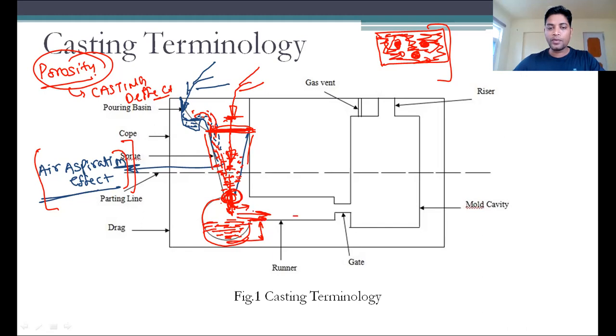then it passes through this runner. This runner is a horizontal passage, okay. And we also use this runner because now the material is moving horizontally. So what will happen in the material, the more dense particles will try to move at this area, a particle which has a very high density will try to settle over the bottom of this runner, and the particles or molecules which have a low density will try to lift to the top position here, okay. So this is bifurcating the runner. In other words, we can say it is bifurcating into the high density particles and the low density particles.